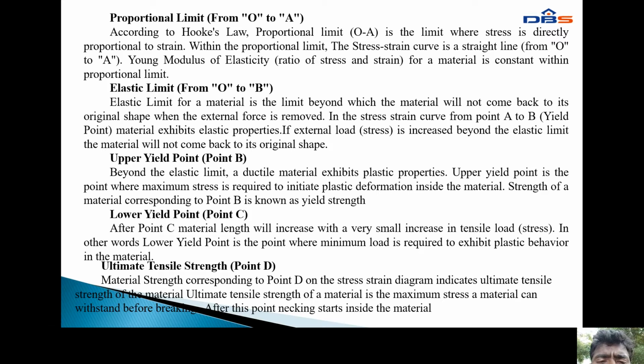before breaking. After this point, necking starts inside the material. After the ultimate strength point, necking is started inside of the material. In this slide, we can explain the proportionality limit, elastic limit, upper yield point, lower yield point, and ultimate strength.